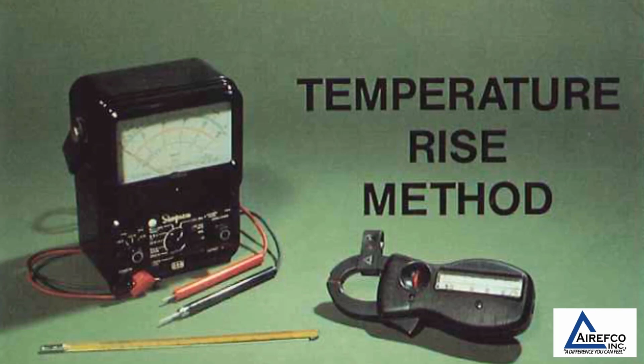Just last week, I was talking to a tech, and we determined that the problem was airflow. And I was asking him to check his CFM, and he had no idea how to do that. So hopefully these few slides will give you an indication of how you can check CFM on a system that you're working on.